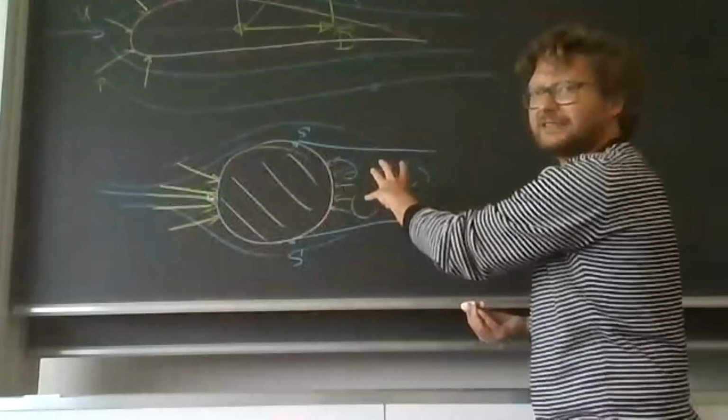So in total, we create a drag force D, and I put an index P to indicate this is a contribution only from the pressure difference. This is the pressure drag contribution. It has nothing to do with viscous friction forces. I mean, indirectly, yes, because of flow separation and all that, but in the first place, this drag comes only due to pressure differences upstream versus downstream.